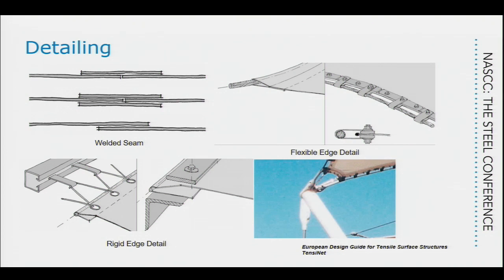Yes, there are materials that will stretch more, and if you're familiar with the elastic modulus in steel, it tells us how much we can stretch steel, right? Here, you get two parameters from the manufacturers: a modulus of elasticity of the material and what they call the apparent modulus of elasticity. Because the material is woven, there's a little slack in it when they fabricate it, so when you start to stretch it, it deforms without much load on it.